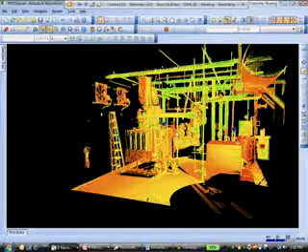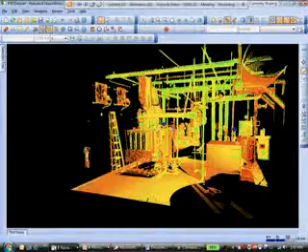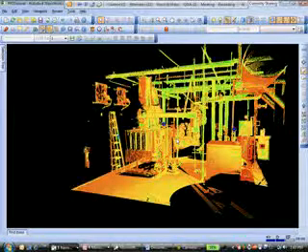But what's important to remember is that's the raw data. When I pull this into Navisworks and make changes, such as changing the resolution, it's going to cache that file into an NWC file, which is going to be significantly smaller. So depending on the resolution I have set, the raw data file itself is fairly large. It can be several hundred megabytes, and it could be even significantly larger depending on how much is encompassed, as well as the detail and the size of the scan.